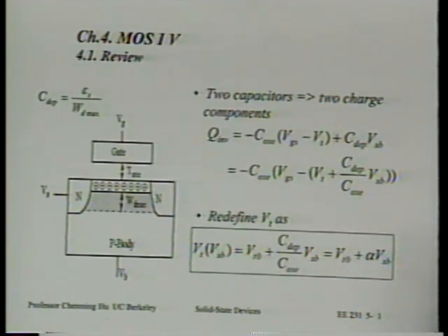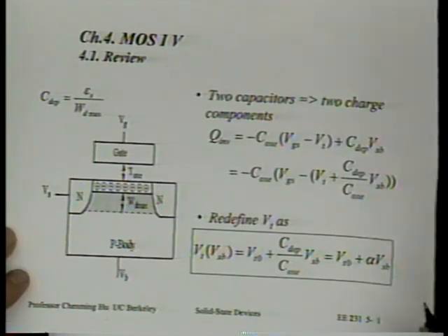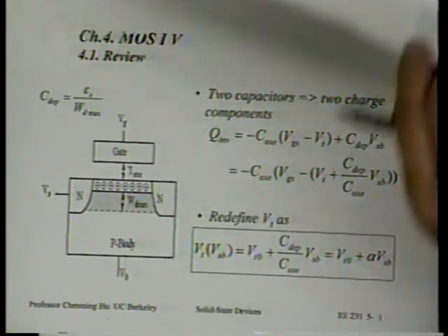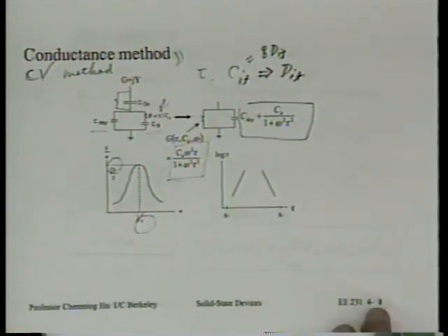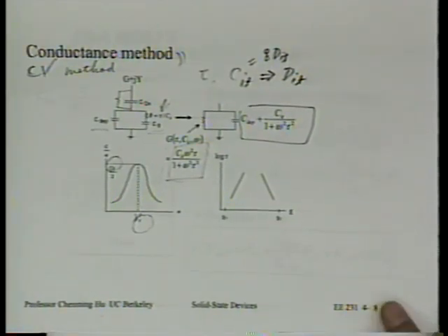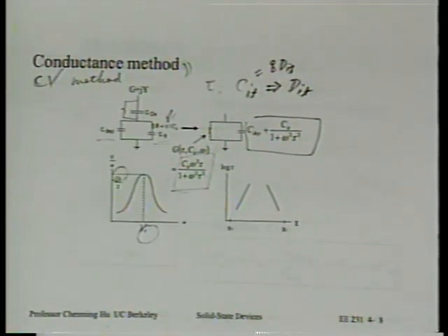Why wouldn't the time constants be separable? Meaning that even if you have a leaky dielectric, the time constant of the gate oxide and that leakage, why would you assume that that leaky impedance would interfere with the measurement of a much lower frequency time constant? I probably don't have a complete answer for you. As I said, this is a new problem even for me to think about. I did not particularly emphasize that measuring the time constant is a problem. What I said is that in general, characterizing the interface trap is a problem. For example, just getting DIT is a problem.